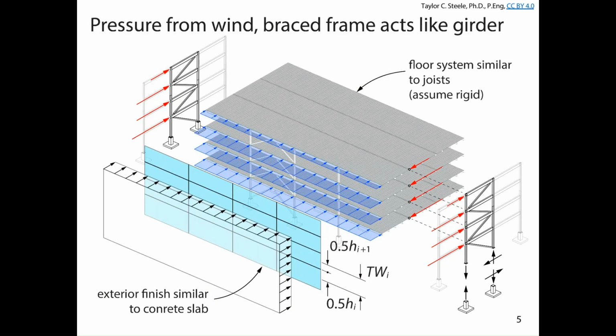And we looked at this picture in lecture 4 sometime last week. Basically, on the windward face, we're going to more or less assume that the pressure is uniform. On the leeward face, we're going to assume that there's a uniform negative pressure or suction on the back face. That's not shown here, but we're basically going to assume that in this wake region we can adequately treat that as if it's a uniform suction along the back face.